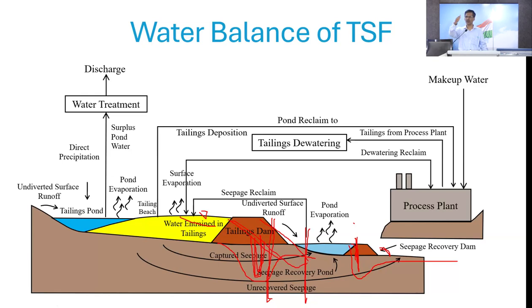That's why I need, when you are talking about yesterday's piezometer, at least the same line, at least 2 piezometers. Otherwise it is very difficult to know how the flow is going on. Then from this, because the problem was here, the water table was here from outside. That level is being maintained here rather, and this has no relation with the internal.